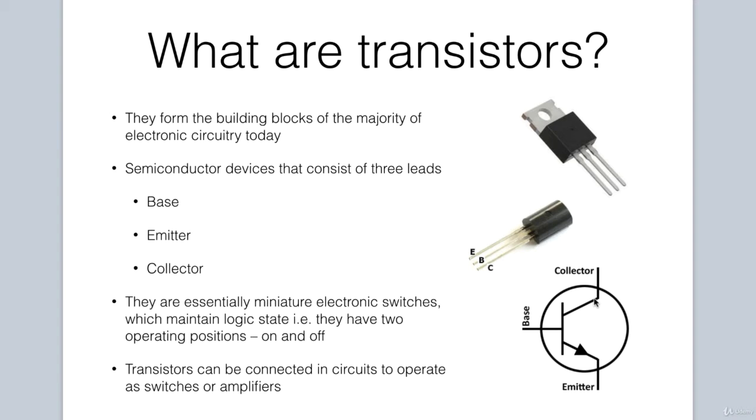Transistors usually have two main modes of operation. They can be used as switches to quickly switch a circuit on and off via an electrical signal. This can be controlled very accurately, up to thousands of times a second. And they can also be used to amplify signals in a circuit. In our circuit, we are primarily using the transistor as a switch to turn our motor on and off.